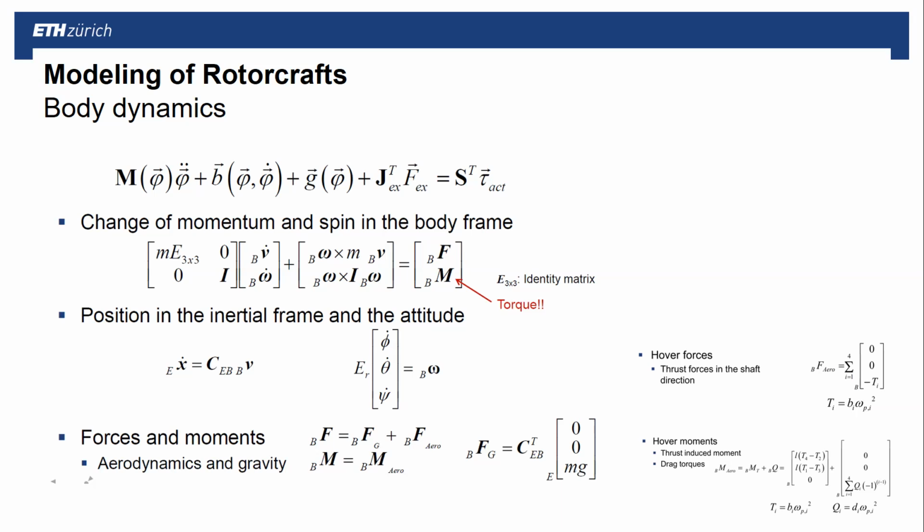So we have thrust from the 4 props, and then depending on the rotational speed of each prop, they produce different drag forces. If there's an imbalance in the velocities in the different directions, you get an imbalance in the drag around the yaw axis, and that on one side allows you to turn it, on the other side is also something that you have to correct. So you do a thrust allocation among these 4 props in order to steer the different degrees of freedom.